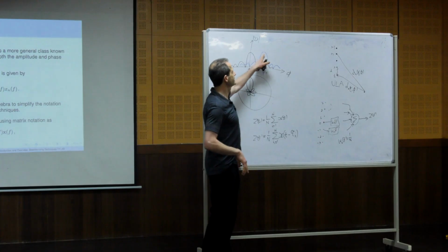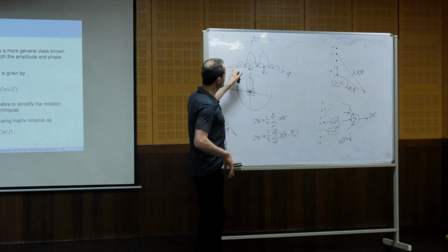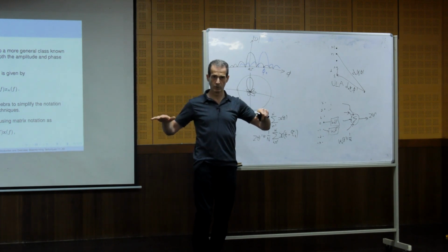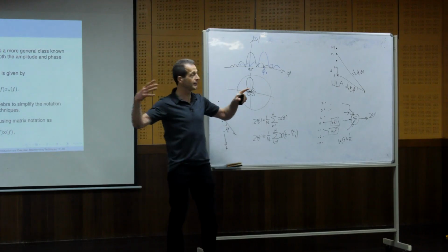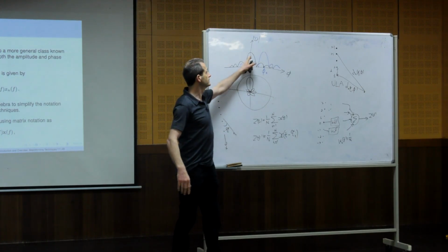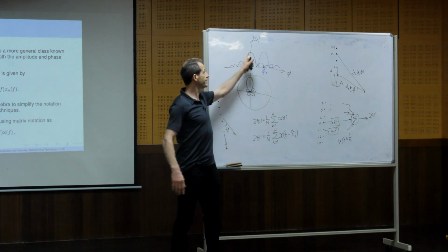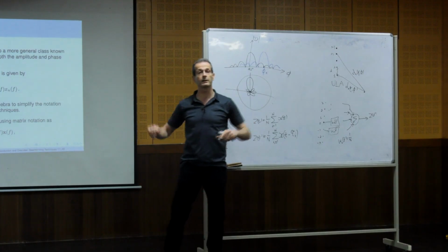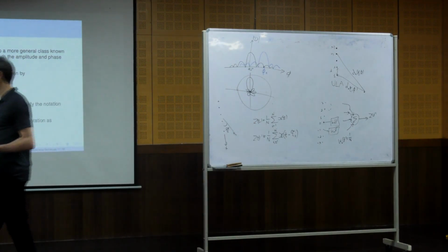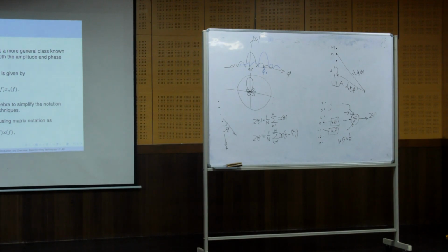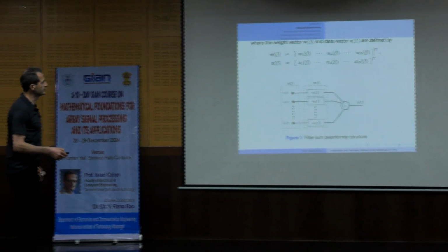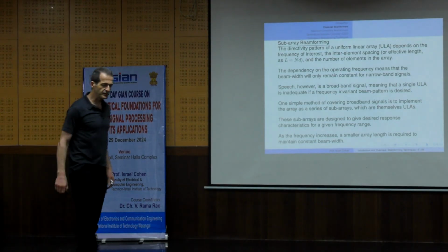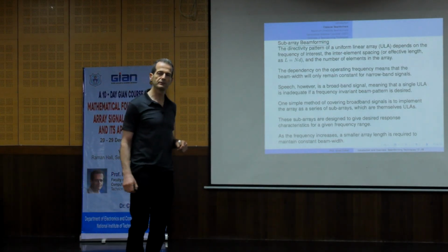If it maximizes this ratio, it means that the side lobes will be as low as possible, which means that for all noise that comes from directions outside the main beam, the gain will be as low as possible, which makes sense. Okay, so this is how it looks. Okay, another issue, so we will talk about the maximum directivity beamformer.